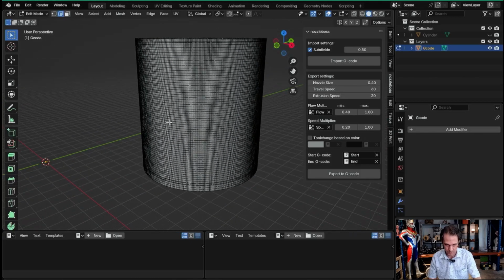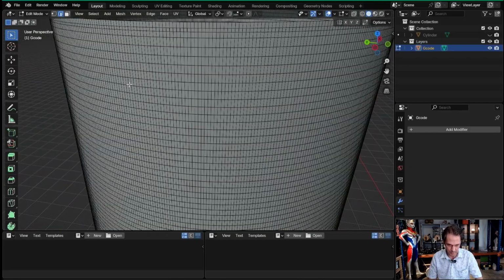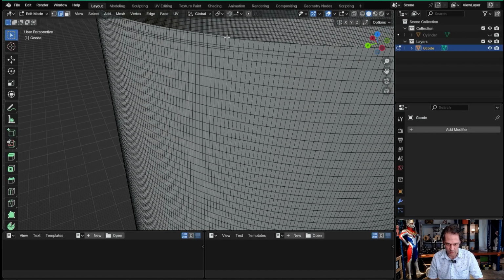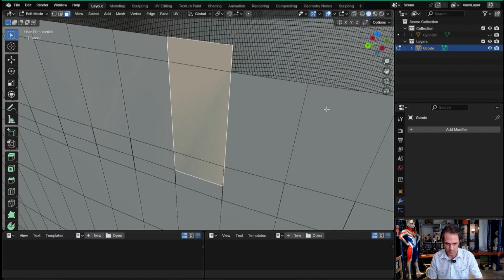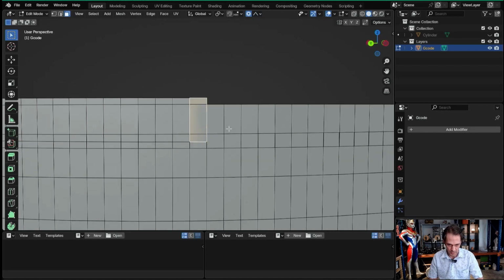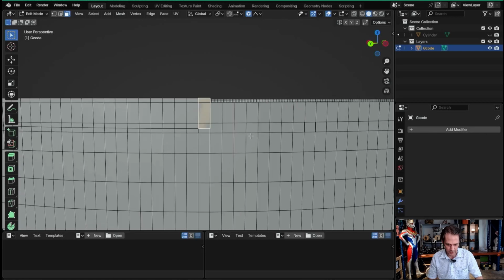So now it should be one complete spiral, but it's still overlapping a little bit. What I do is I go into face select, view selected, connected only, linear, and what I want to do is create a nice finish to the top of the pot. So I want to reduce the extrusion rate and not lift up the nozzle height as fast for the last bit, just to create a leveling off at the top.